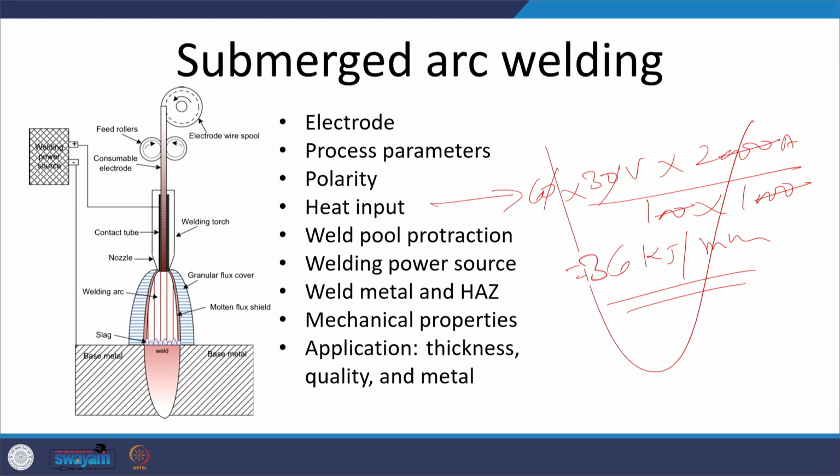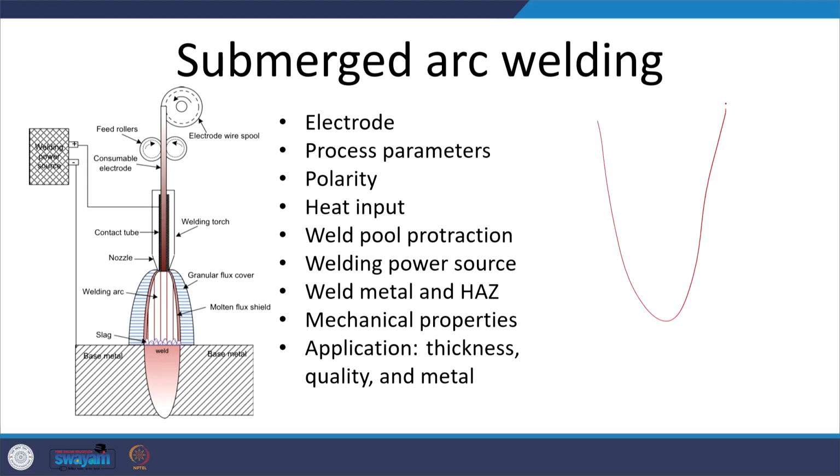When we use high heat input, certainly it will increase the depth of penetration, but it will also increase the weld cross section and the heat affected zone width. So, there are many adverse effects associated with high heat input, despite the advantage of the ability to weld thick sections in one pass.